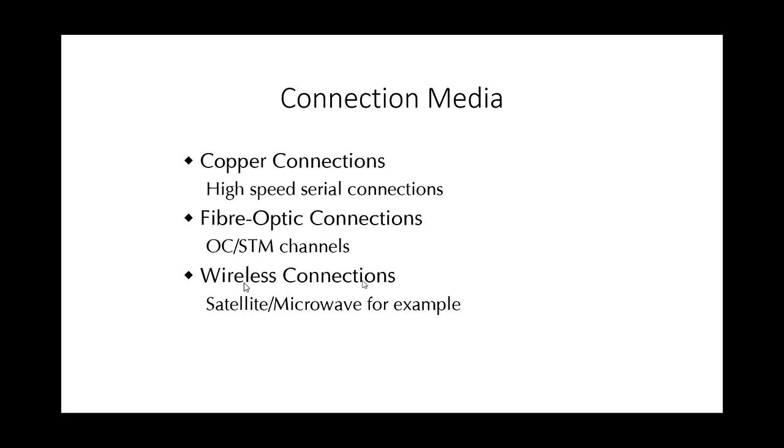In the US, 24 of these channels are bundled together in a DS1 channel, carried over a T1 connection. This provides a capacity of 1.536 megabits per second. However, 8 kilobits per second are needed for synchronization, which is used to separate the channels.